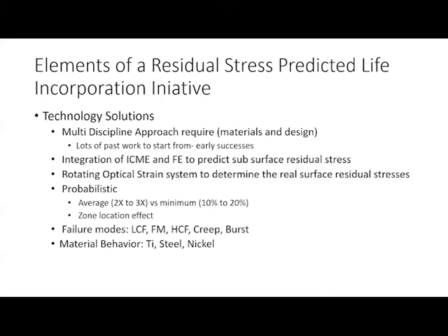So the elements of this residual stress prediction, I think it's going to take a multidiscipline approach. It's going to take both materials and design. I talked about this integration of integrated computational materials engineering and finite elements to predict the subsurface residual stress. Remember, I've stated a couple times, I'm not aware of any ability to predict subsurface residual stress accurately without doing some kind of destructive testing.